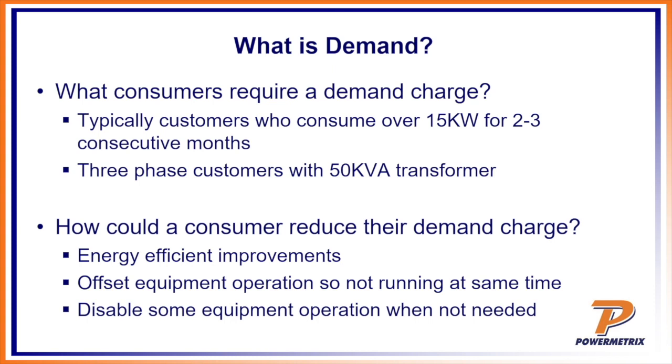I polled some of the customers about when they actually switch over to a demand customer. This particular customer told me that anybody over 15 kW usage over 2 to 3 consecutive months was considered a demand customer. Or if they're a 3-phase customer with a 50 kVA transformer. That's a pretty good size customer, right? Because that's 150 kVA per phase, it's a bank of transformers. So yeah, that's pretty large.